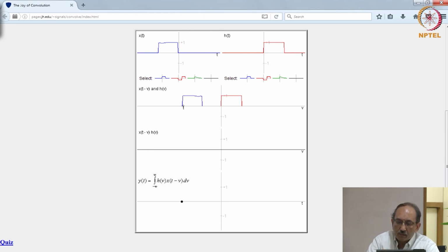So, right here is the flipped and shifted pulse. Notice now where this T is attached to. It is attached to the origin of the first pulse, right, and now you see the reference point is here, and now when I start to move in, at this point of shift the overlap starts to happen, and when I slide it across I get something like this. Now, you see the difference in these two cases, and where this variable of shift T, which is what determines the output, is. So, this clearly illustrates the difference between these two cases.